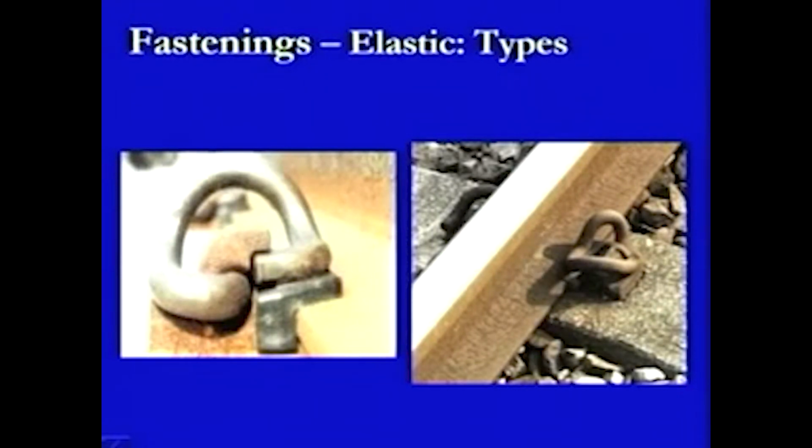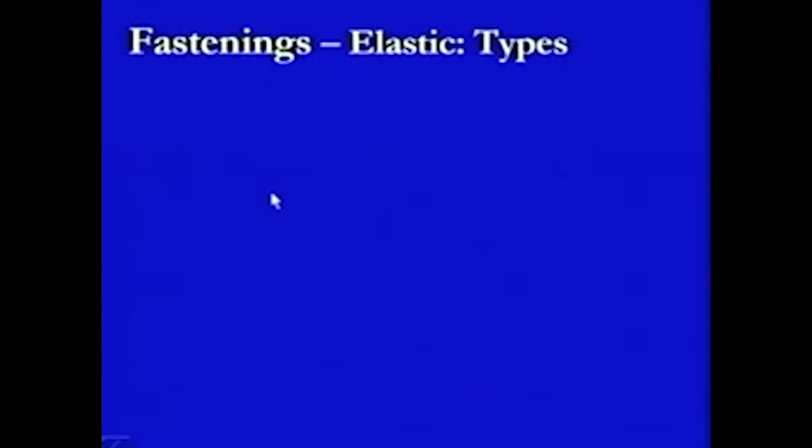This pressure has to be created while fixing these Pandrol clips in this location. The Pandrol clip goes inside this section in this way, and if you take out this one, then everything is out. Therefore, it is a theft prone condition in the Pandrol clips.